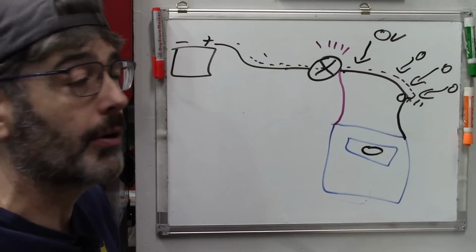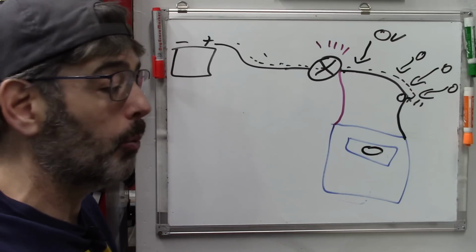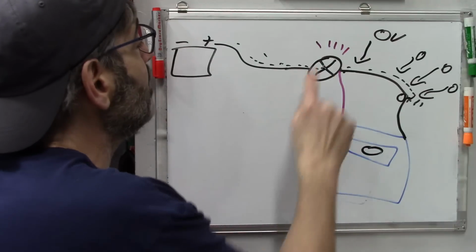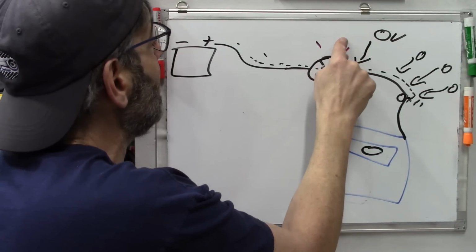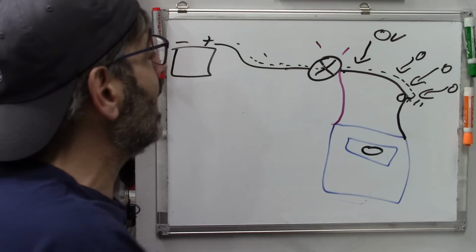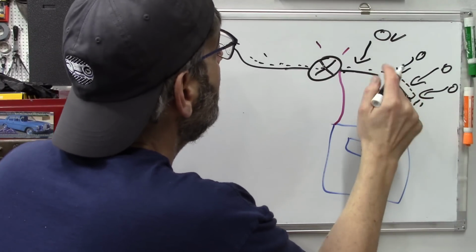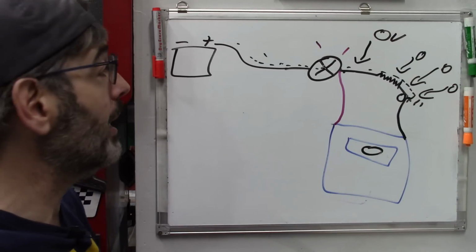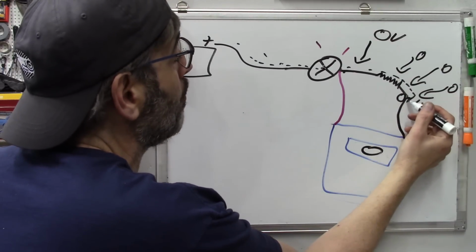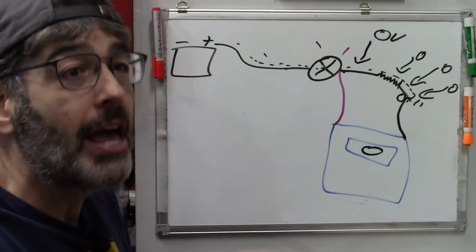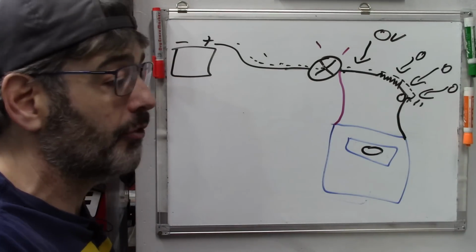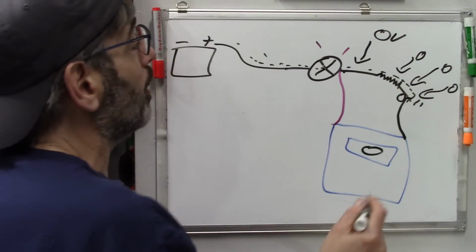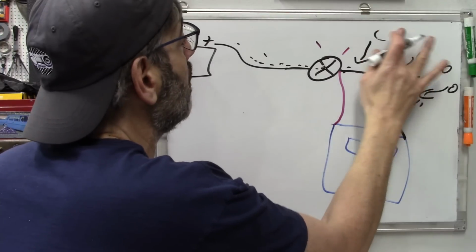We should read 0. Now, why would we want to do this? Well, what I believe your instructor is trying to do is show you that if this bulb is not lit up as bright as it should be, one explanation could be that you have a resistance in your ground, which is pretty common, and very often that resistance is going to be where the ground actually connects. If you have a ground to the frame of the vehicle, for example, that's very often where you'll find this. Well, if we have a resistance here, remember what we mentioned earlier. See, it's all coming back together.